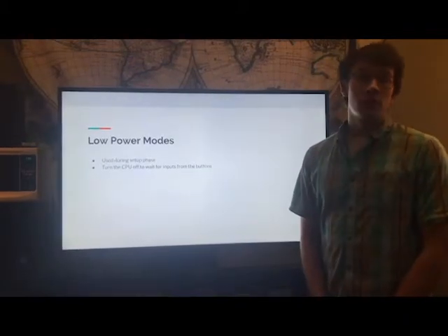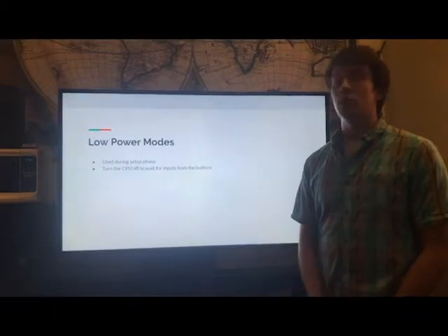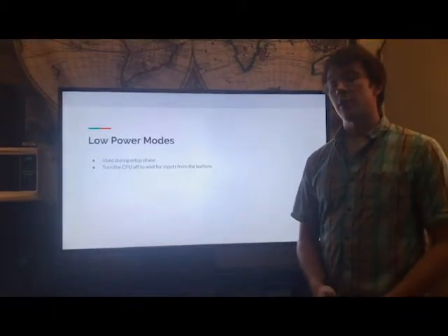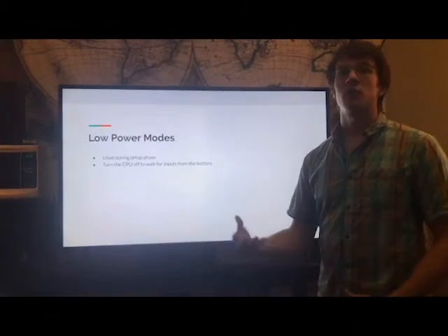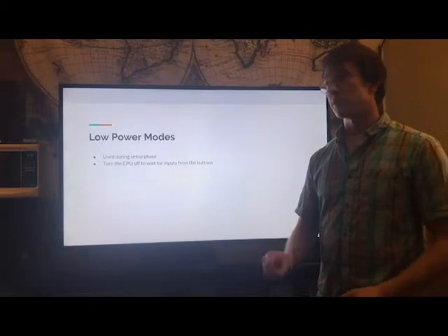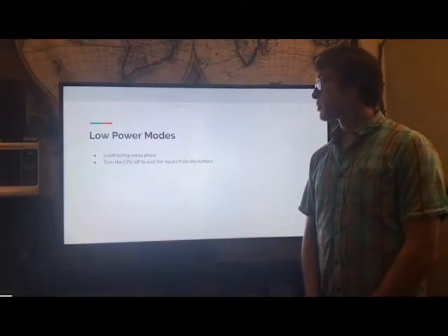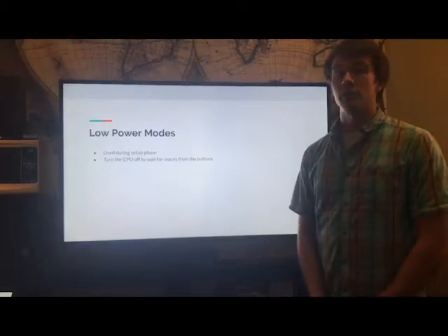Low power mode was also important because we wanted to use the technique of turning the CPU off to wait for interrupts from the buttons. This was helpful for waiting a variable amount of time for the user to hit the next button to determine what the next control process is in terms of moving the LED around for selecting. And by turning the CPU off, it saves power and is a convenient way to wait for user input.